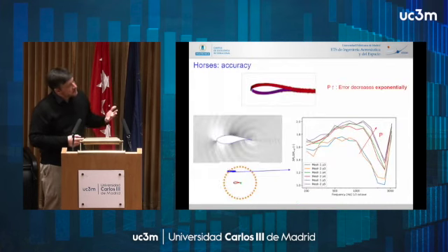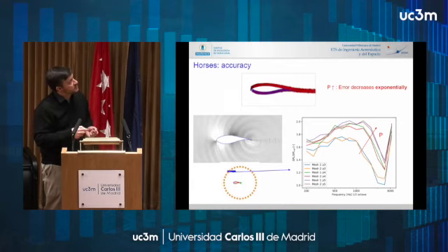Furthermore, we have tested that even further for more complex problems. If we look at the acoustics of an airfoil, for example, this has an LES model in it, so this is a much more complex problem, and we're looking at the acoustics. That's the acoustic waves that emanate from the trailing edge and then propagate up to certain locations where we're measuring the noise, and we can plot the sound pressure levels against the frequency for this particular location.